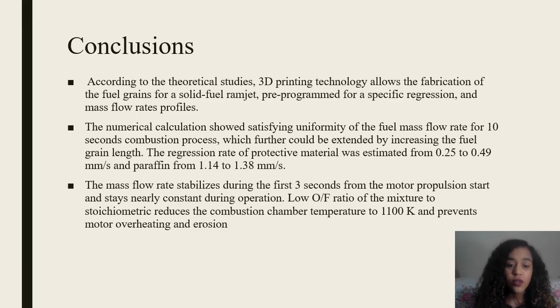Conclusions. According to the theoretical studies, 3D printing technology allows the fabrication of the fuel grain for a solid fuel ramjet, pre-programmed for specific regression and mass flow rate profiles. The numerical calculation showed satisfying uniformity of the fuel mass flow rate for a 10-second combustion process, which further could be extended by increasing the fuel grain length.